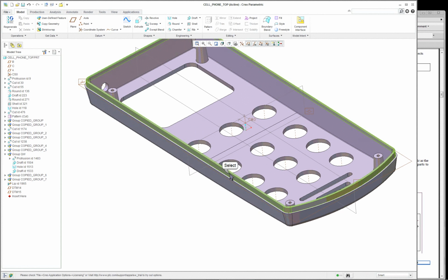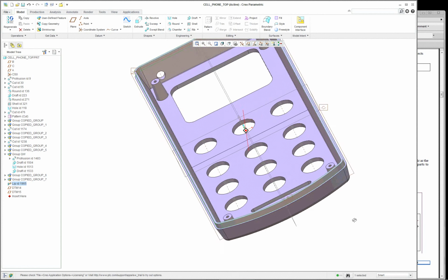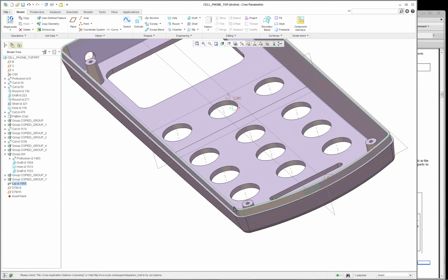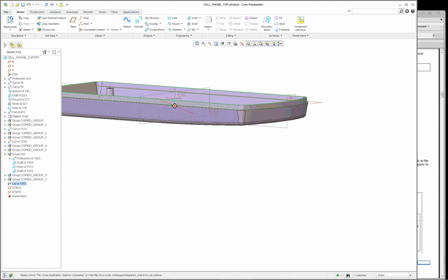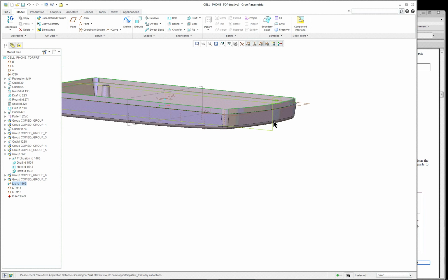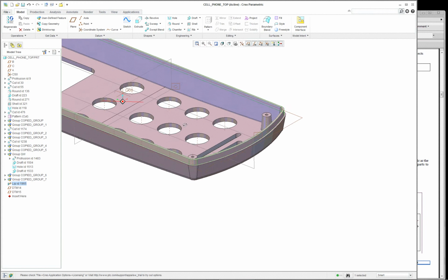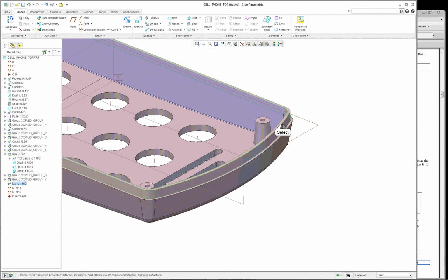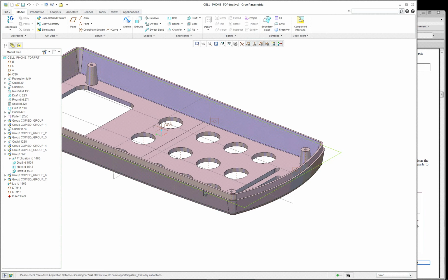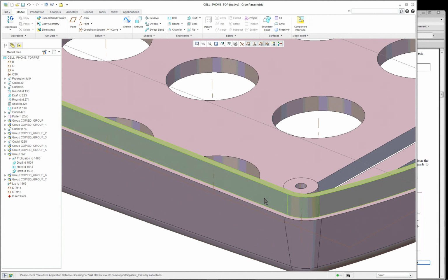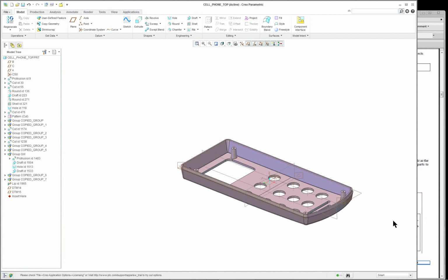But basically all it is is a sweep cut that goes around. Take that back. Let's see. It's a sweep added. Well, it's not a cut. It's an added feature. So it's an extrusion. But you can do it with a sweep also. Sweep it around and add that portion, using the edge here as the sweep profile trajectory.